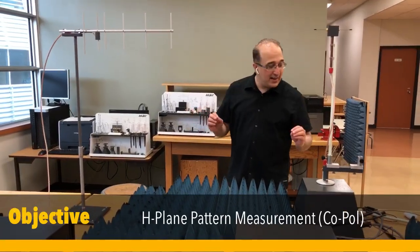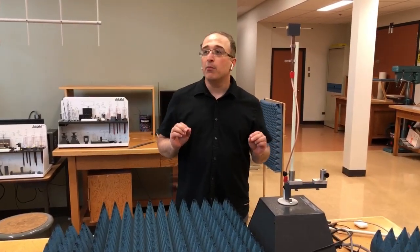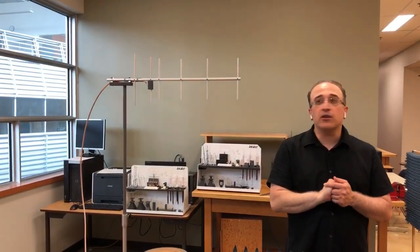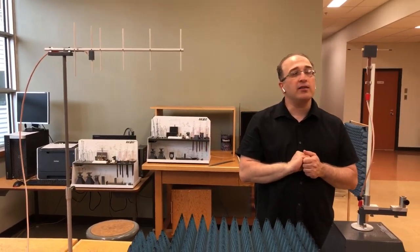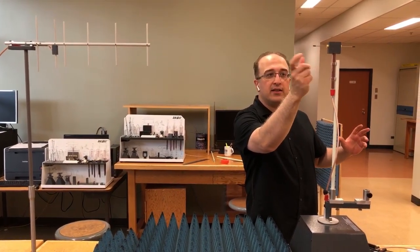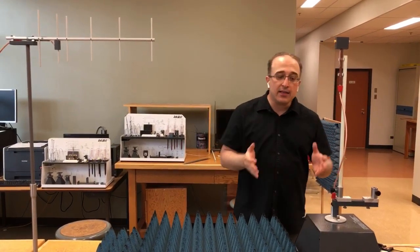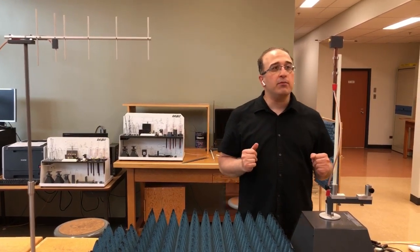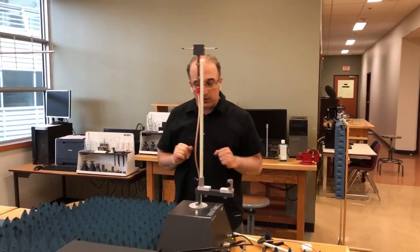Okay, so the last step that we covered was the E-plane measurement, but in the cross-pole. We rotated the transmitting antenna 90 degrees so that the polarization is not matched to the dipole antenna, and then this was rotating in the azimuth direction, and that became our cross-pole E-plane. Now, in this step, we want to go to the H-plane pattern measurement. To do the H-plane measurements, we should move this antenna and put it in a different orientation.